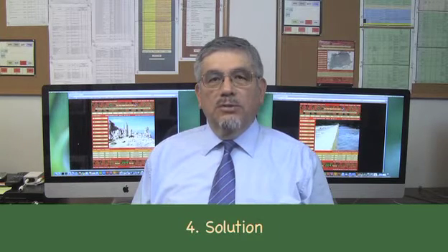Decomposition includes the processes of 1. Carbonation, 2. Hydration, 3. Oxidation, and 4. Solution. Carbon dioxide in the atmosphere readily combines with water to form carbonic acid. Carbonic acid reacts with feldspars to produce clay minerals, silica, calcite, and other relatively soluble carbonates containing potassium, sodium, iron,